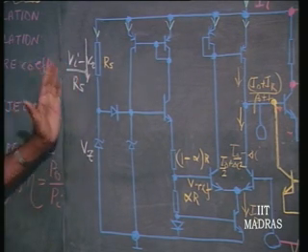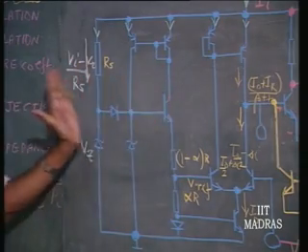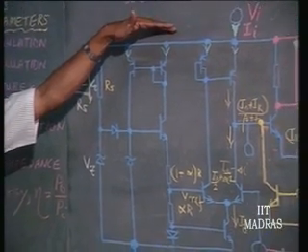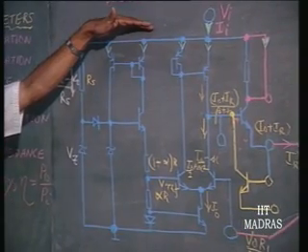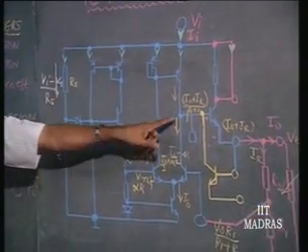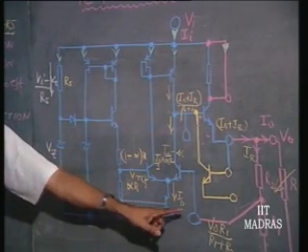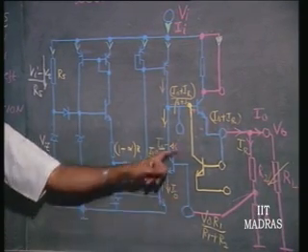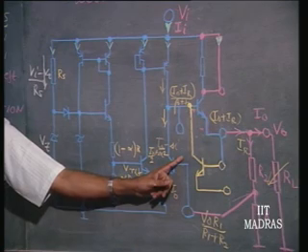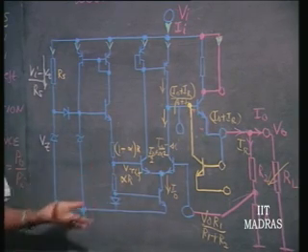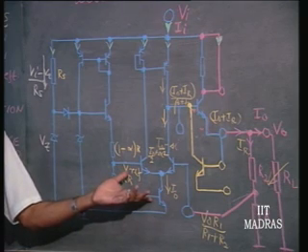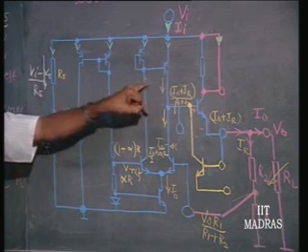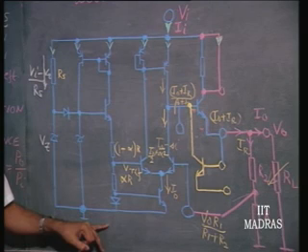Understood? So you have to be very, very careful in your design. At all points you have to see, if I increase this voltage, is there any device that is going to break down? The bottom transistor always has the collector voltage less than V reference. Which one? The bottom transistor, this one. This one is not a problem at all. It is this transistor alone which will have the problem. And this you have to identify because we do not know how the various transistors are connected. Actually this is always at V gamma less than this, and this is always at V reference.